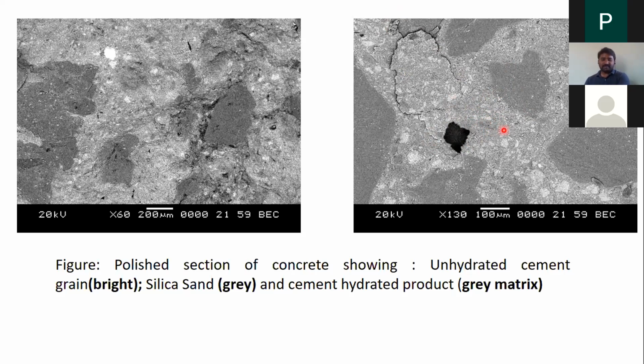Or else just remember, the brightest part will be unreacted cement, the next brightest will be calcium hydroxide, then CSH, then sand particles, and after that it will be pores.